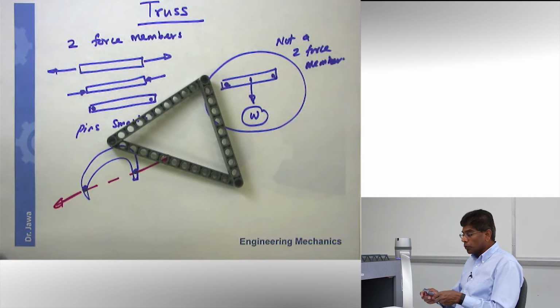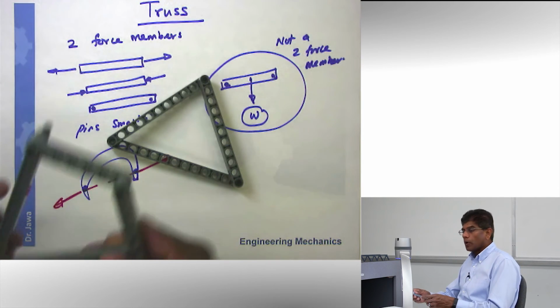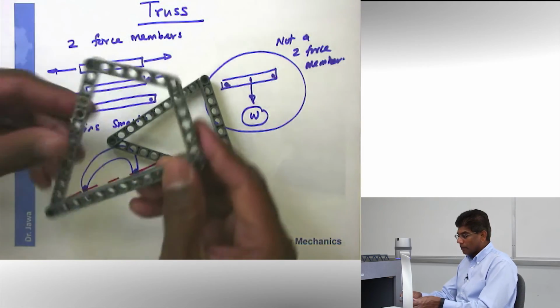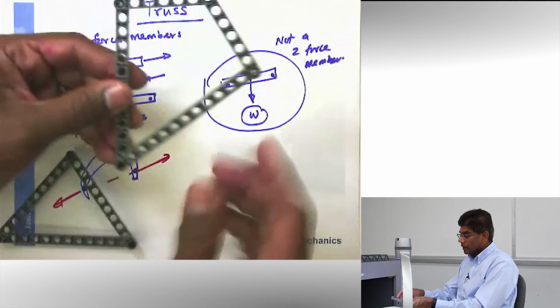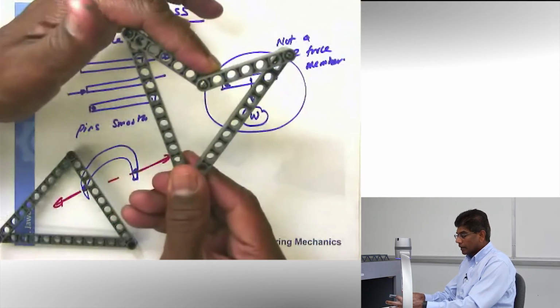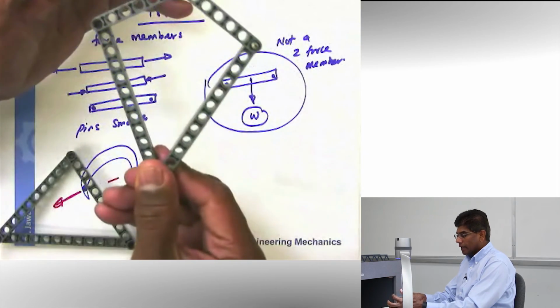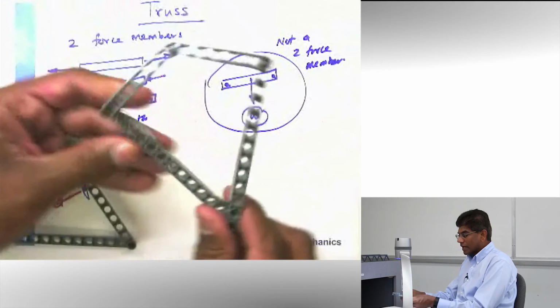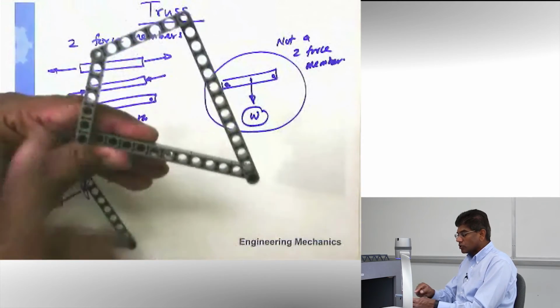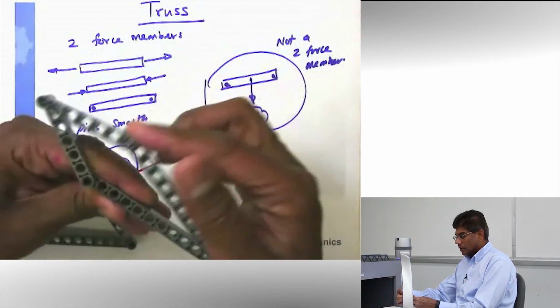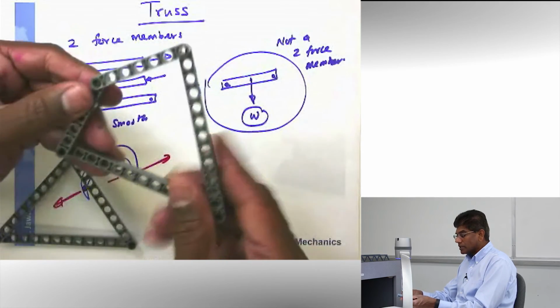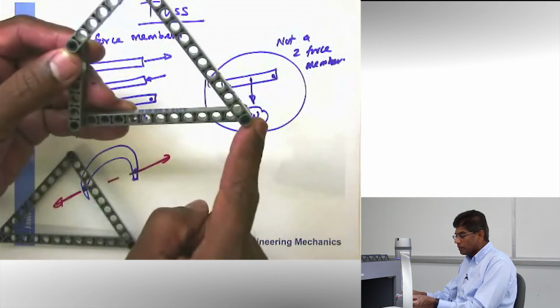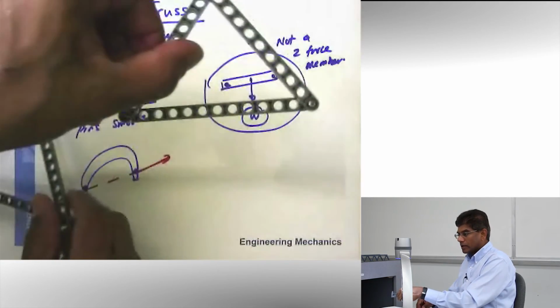And for those of you who think, how about we make a structure with 4 members? If you look at 4 members here, clearly if I give a push here, this is losing its geometry. It actually collapses. So when you have 4 members like this, what you have is not a structure, it's a mechanism. All right? So if you want to make this a structure, you need to put in a cross beam, making it a triangle structure.